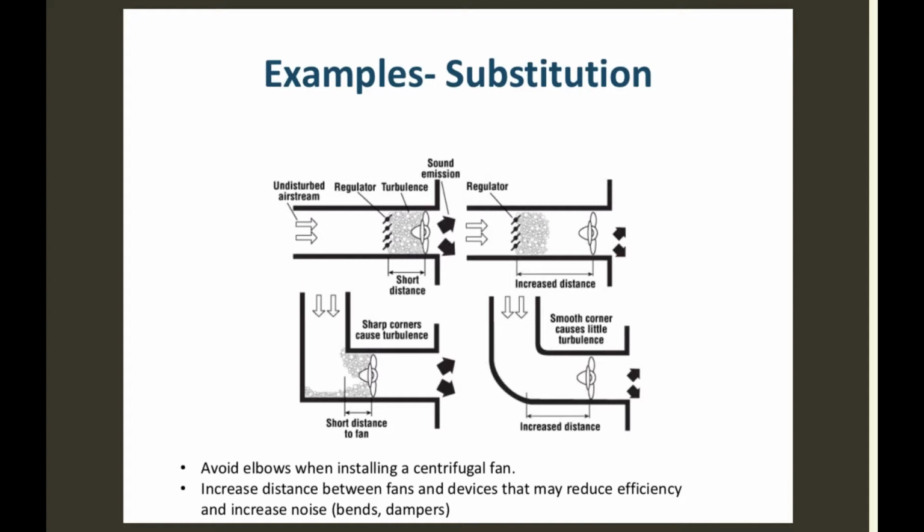The capture duct. So you need to get a little faster. If you're dealing with grinders that are spitting out large particles, you really have to keep the air moving really fast. Keep that stuff suspended so you can get it out of the space, right? But the deal there is that as you increase that velocity, there's more friction inside the ductwork, and you're going to generate more noise.